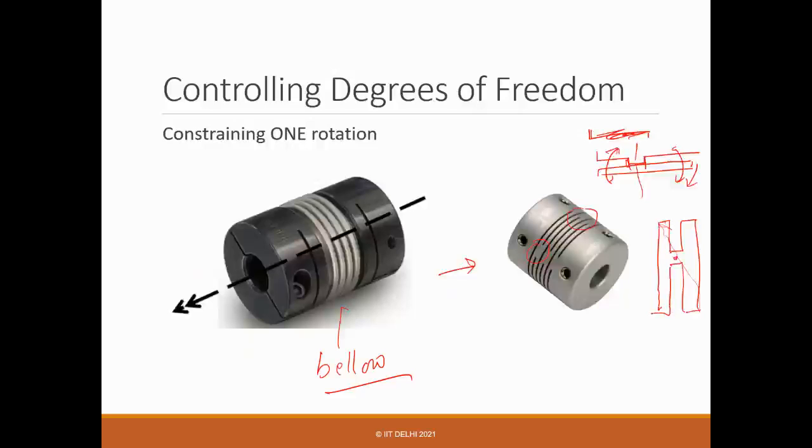And because it's so thin, it will act as a hinge, so it can again rotate. And since it can rotate, and this thickness is very small, it will act as a cantilever, so it can also flex, so you will also get that motion. But torsionally it is very stiff, so it works like a flexure.